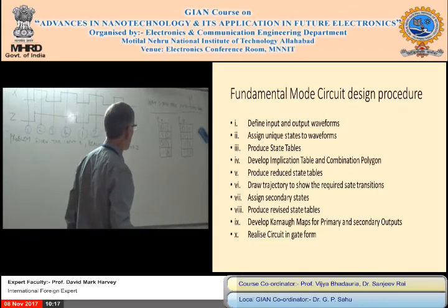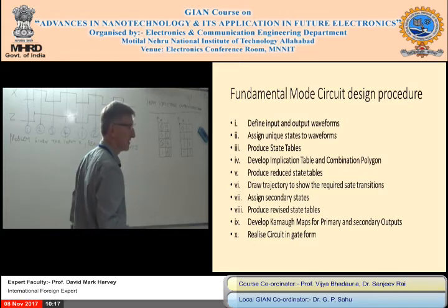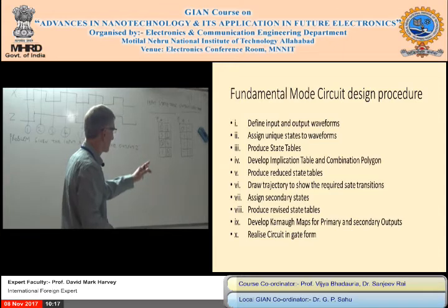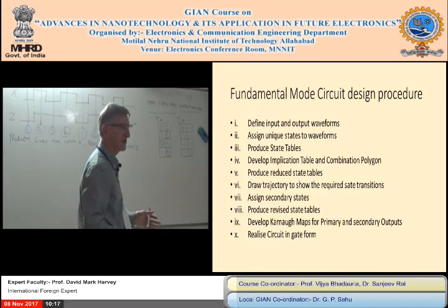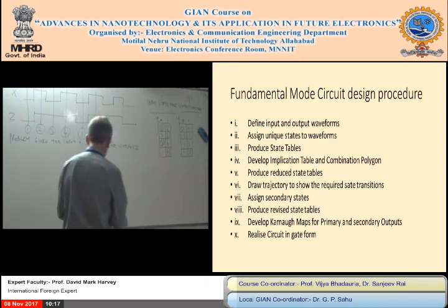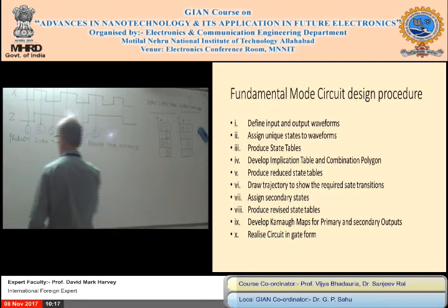And the last one, this is very important. 2 stable states with different outputs can be combined if they exist in different columns. So that means we've got different inputs. So that's different from being in the same column. Anyway, I'll draw up the table.